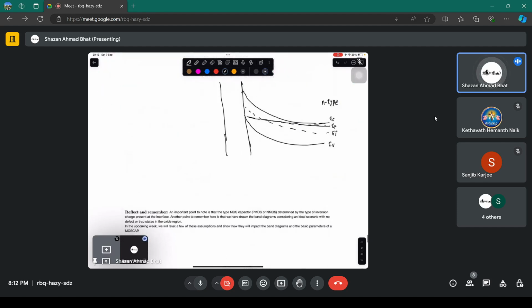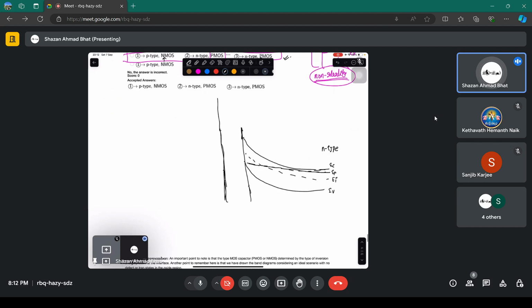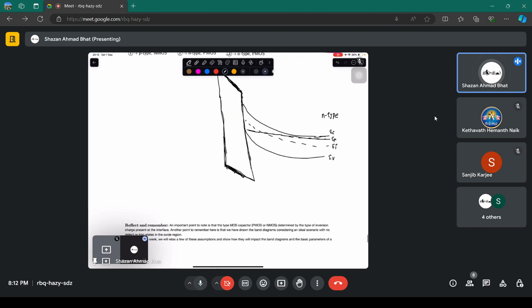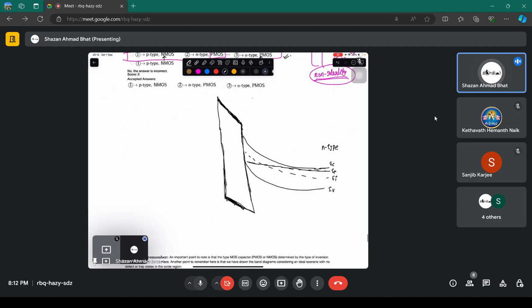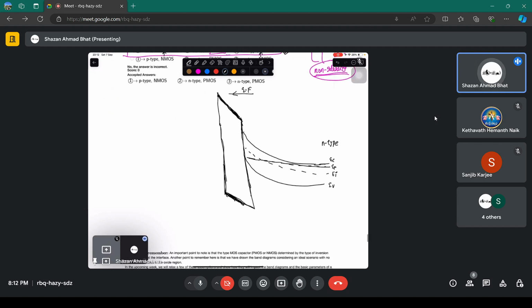तो ये bending कब आ जाएगी इस side से, when you, let's say they have not drawn the oxide, but oxide will bend something like this also, जो कि यहाँ पे नहीं दिखाया है इन्होंने, which they should show because there will be bending in the oxide also. Okay, so the electric field is in this direction. That means you have a positive here, negative here.